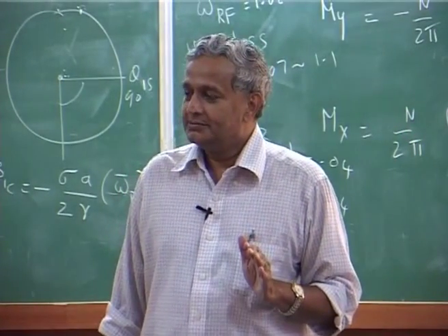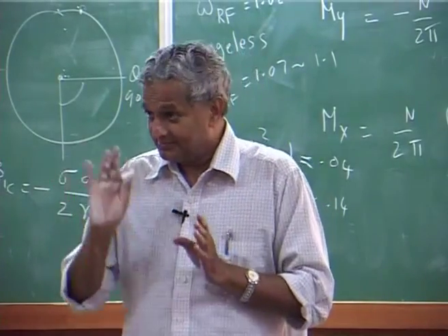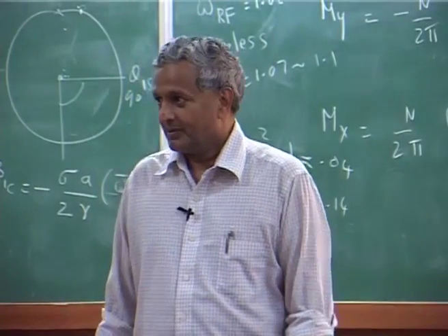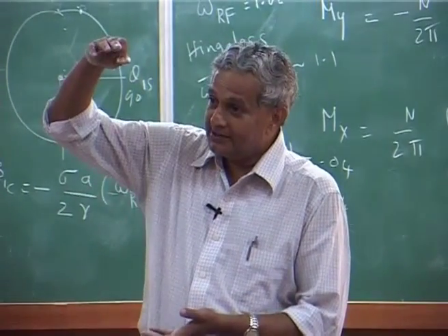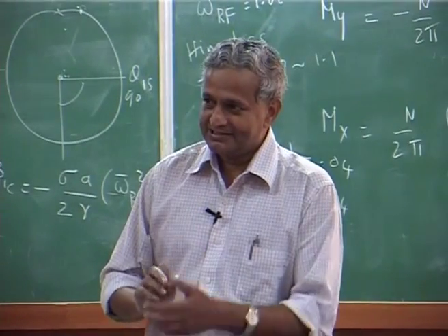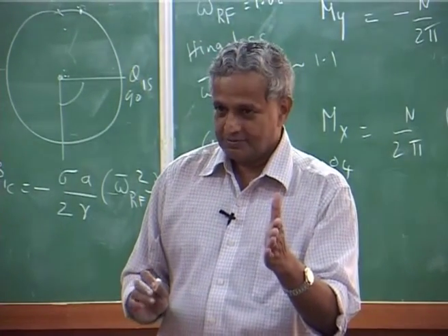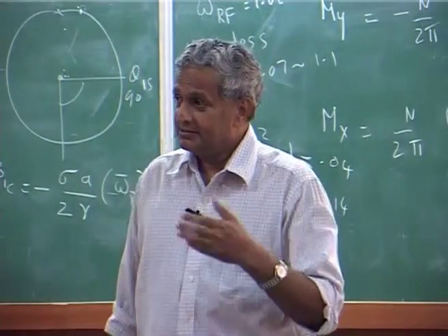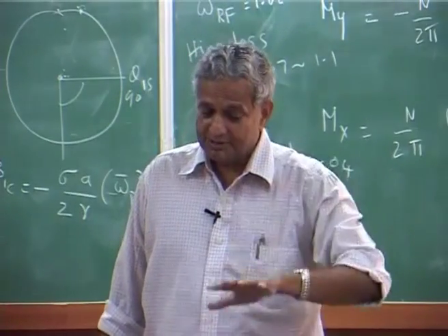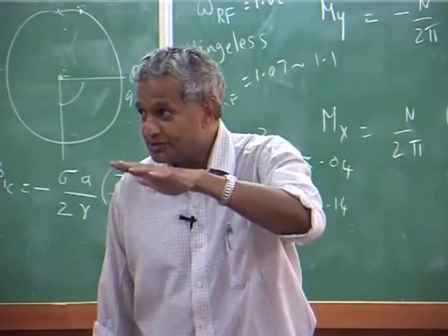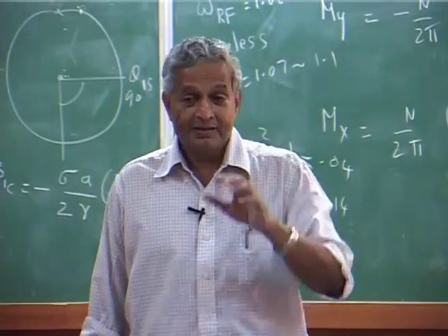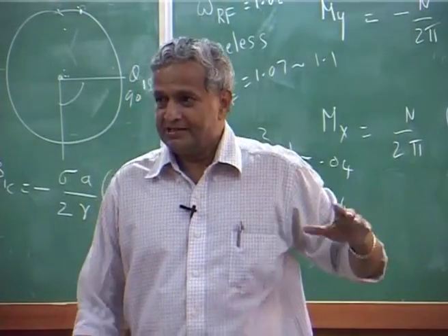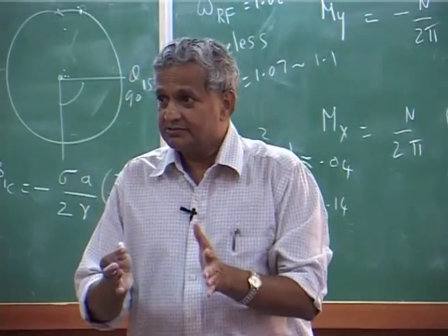Another one is you take only the flap, but include fuselage motion. That means coupled blade fuselage dynamics. You follow? And that has its own set of problems, like you have flap motion coupling with the fuselage, lead lag motion coupling with the fuselage. Each one has its own stability problems. Okay. And then flight dynamics is rotor and the fuselage.